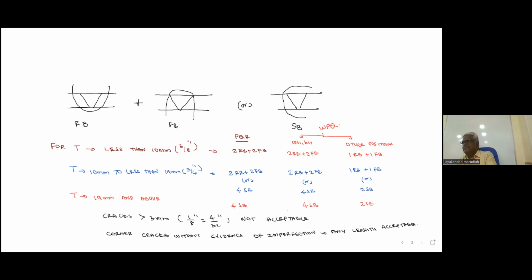Next one is the ductility. Hardness, hardenability, there is no direct relation. Both are entirely different properties. Many people think hardness and hardenability both are same. They are not same. First difference, definition itself is changed. What is the definition of hardness? Ability to resist indentation by plastic deformation. When you press something, if it resists, that is called hardness.